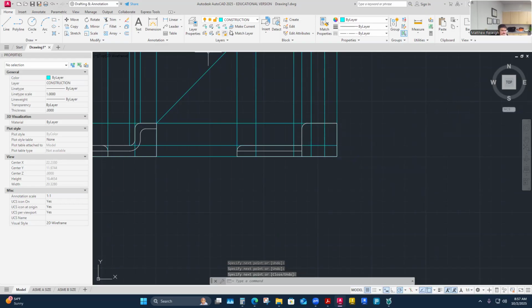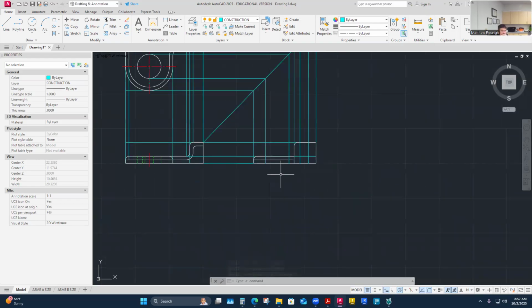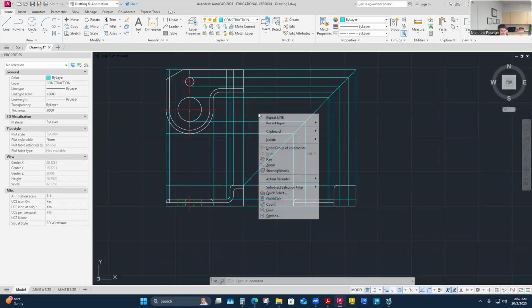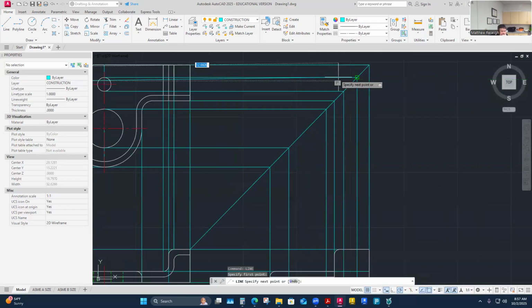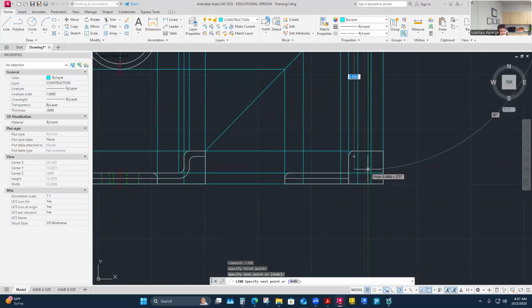And I would see, so if I work on some hidden line work here now, I'll pull those two features down. The other one I would have is one more. I'd have this thing here, right? It's going to show up as a hidden line. It's just going to be really close to the hole. So I got to really be careful that I don't mess up which one's the hole and which one's that.